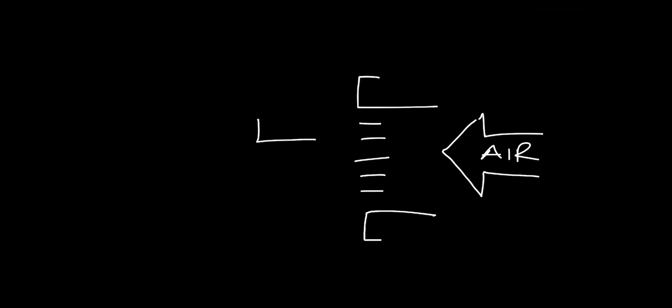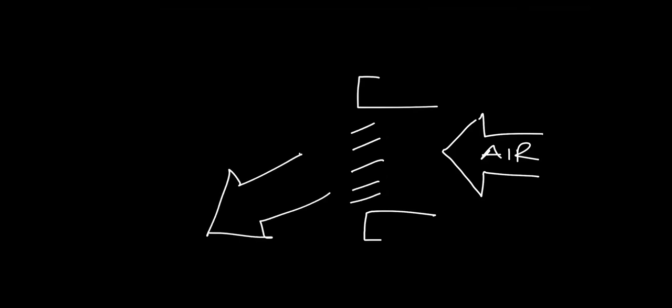The direction of airflow through a grill is relatively unchanged. The blades in a zero deflection setting serve to straighten the air pattern. Adjustable supply grills do have the capability of deflecting the air 20 to 30 degrees in a vertical or horizontal direction.